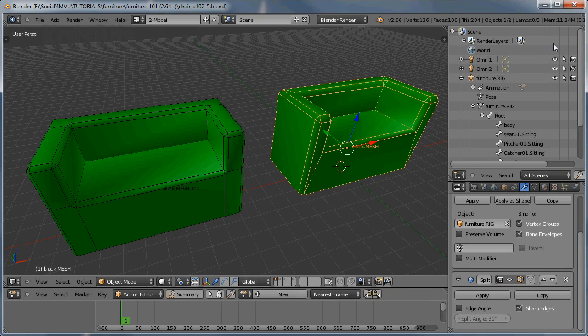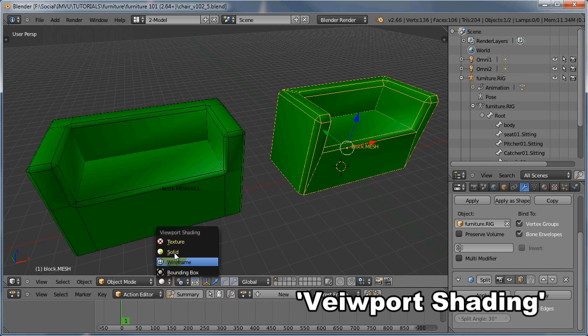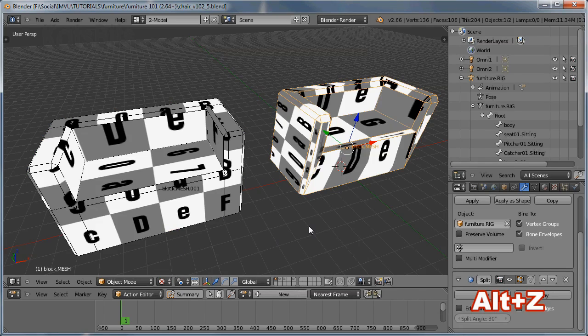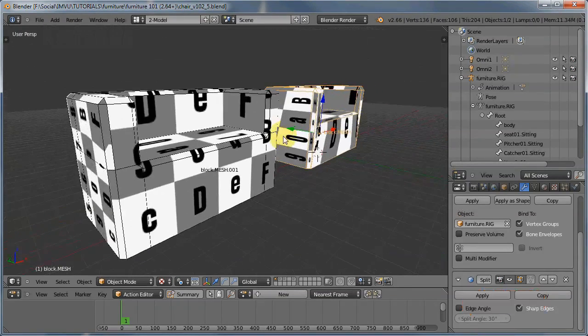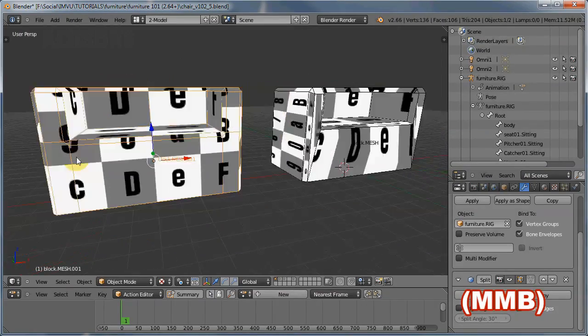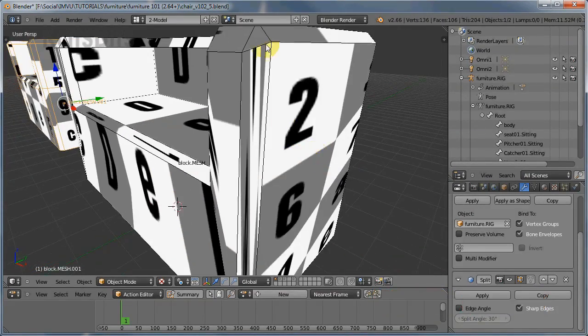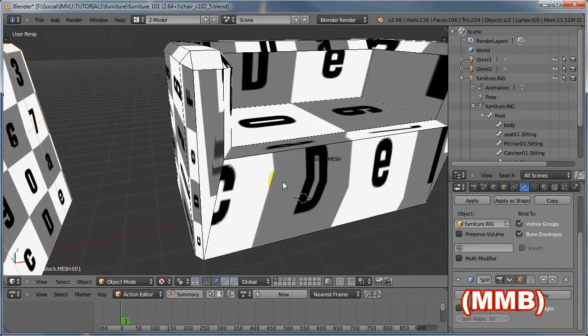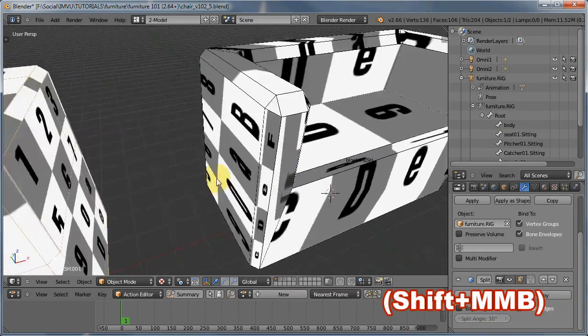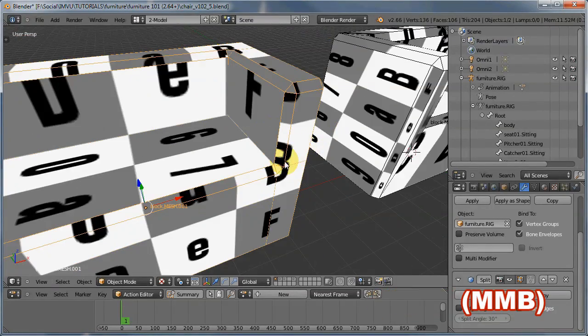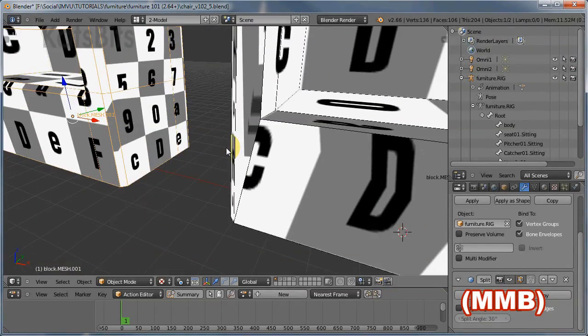Now in editing the mesh, it's likely that this has affected negatively the UV map and texture placement over the mesh. So if we switch viewport shading mode to texture, or Alt-Z, we can see that the bevel version isn't as bad as the manually edited version. We can see a lot of texture stretching and warping present on one but not on the other.